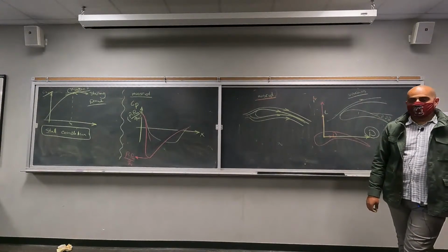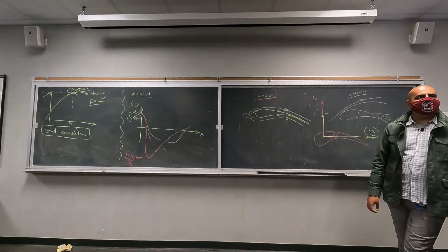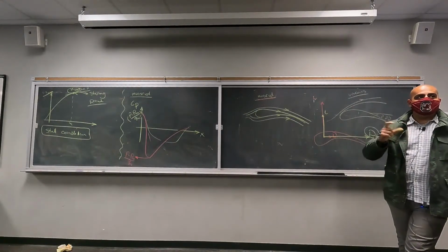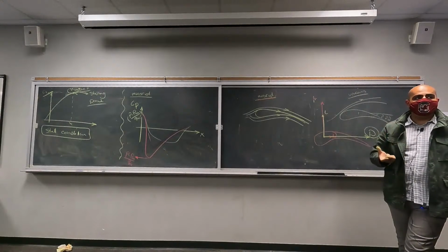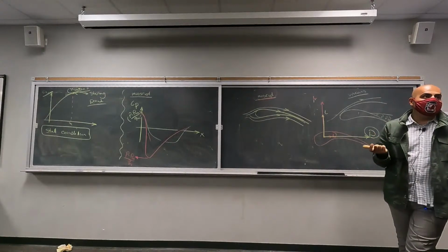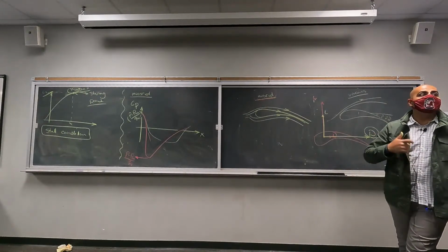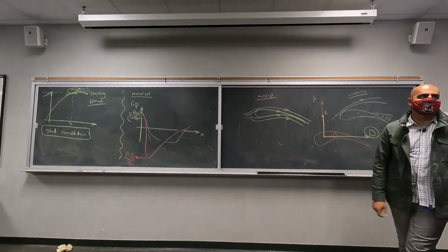So that's a very good question. We will definitely have the adverse pressure gradient, right? But the problem is that the adverse pressure gradient is not going to cause flow separation. That's because the model cannot see any flow separation, since there's no viscosity. That's why you will get very unphysical results.